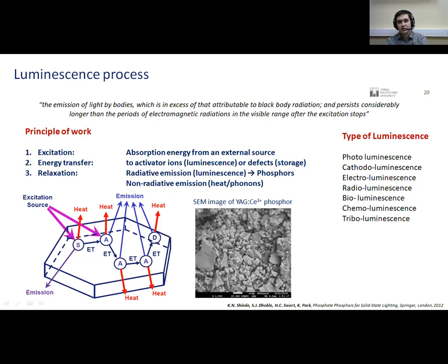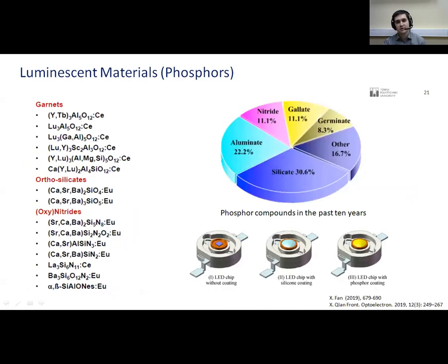As usual, they are mixtures of different types of oxides. The most widespread and really investigated phosphor today is yttrium aluminum garnet doped with cerium 3+ ions. Based on this technology, we can choose the blue LED, put it together with a silicone glue and yttrium aluminum garnet doped with cerium 3+ ions, apply some electrical current to this chip, and receive white light. This scheme is in general applied for any purposes.